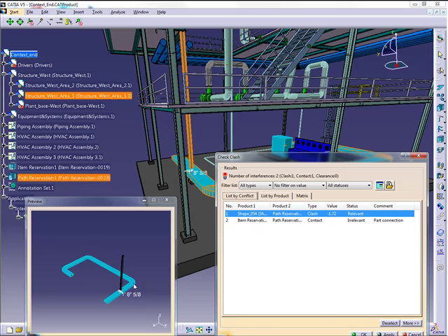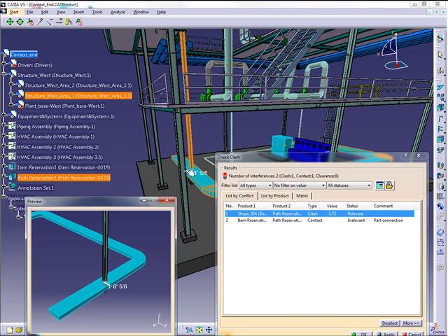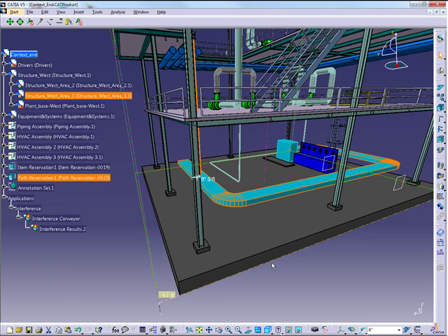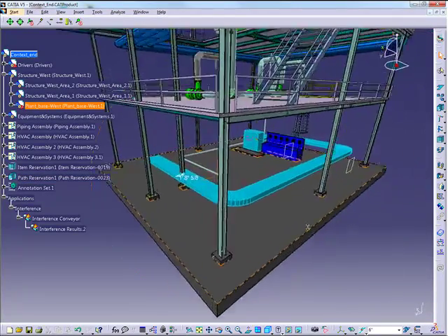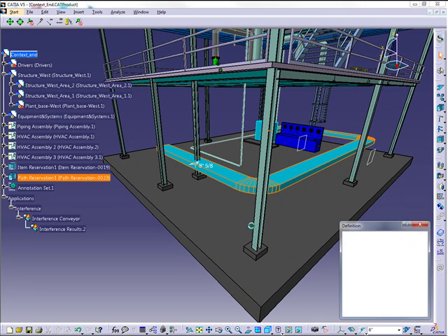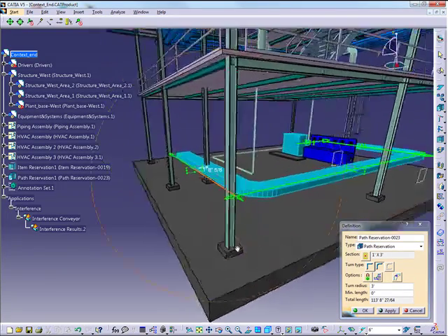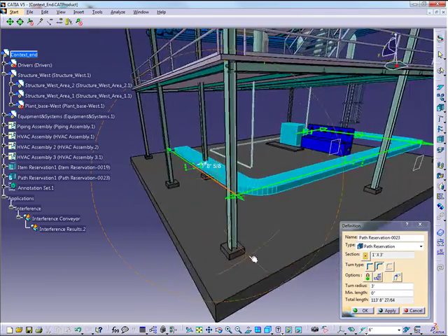And as you can see, Juan's going to zoom in there and show you that the clash in fact is happening. And CATIA will point out in red the cross section of the member where it's being hit. Fantastic. And it highlights it on the model. Alright, so now what I'm going to do, once again, is correct and eliminate the clash by just moving it over a little bit, making sure that it's not colliding anymore.